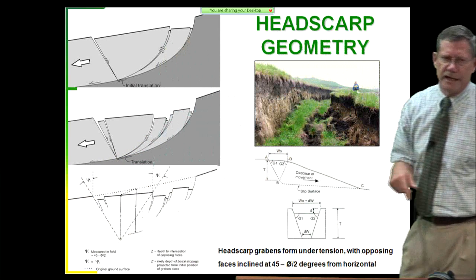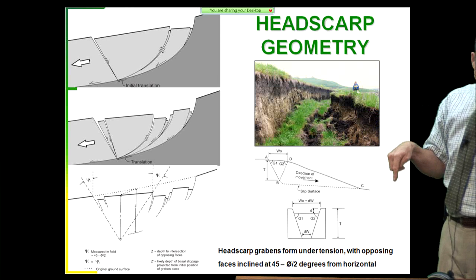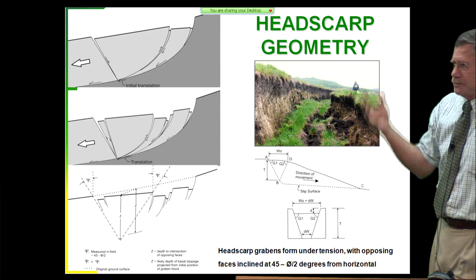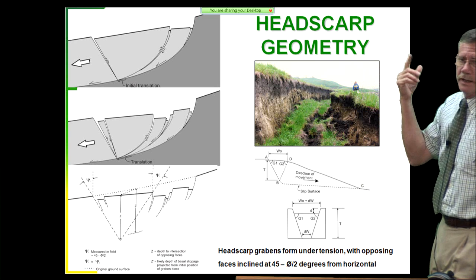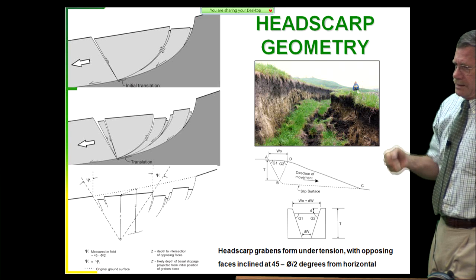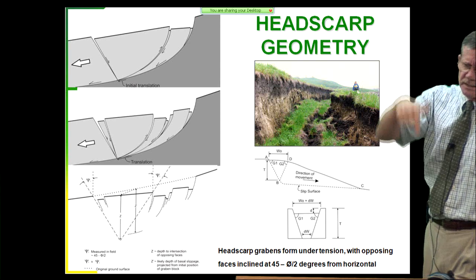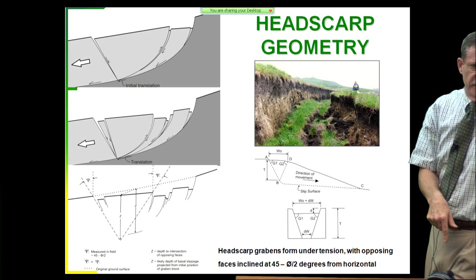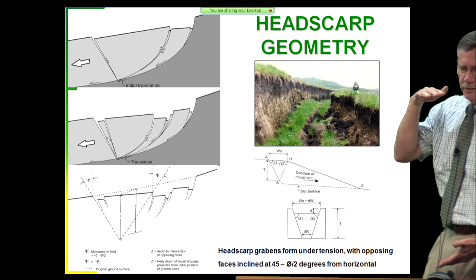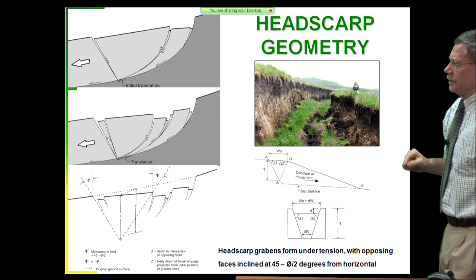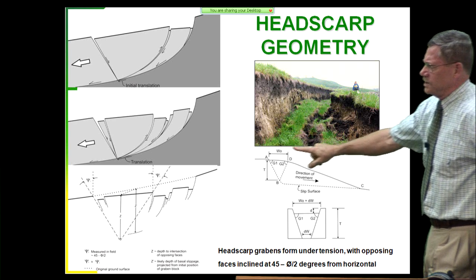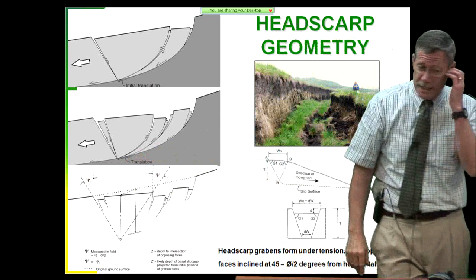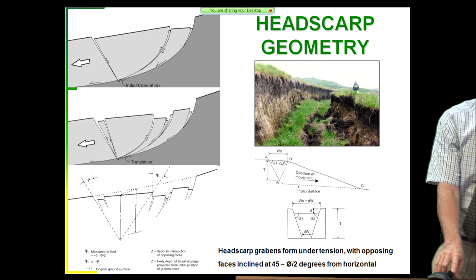Now there's another way of doing that. You would auger first and do what's called a probe. And as you probe down, you probe for the slide plane, you find that, and the driller might say, well, I got a slide plane at 31.5 feet. So they say, okay, pull it all up, move over 2 feet. Let's drill another hole. When we get down to 30 feet, 30.5 feet, we're going to run an 18-inch sampling run, or run a 30-inch sampling run if we're pushing Shelbys, 24-inch, whatever we're going to do. But you always want to probe first, and then you can always do this graphical solution first when you're trying to guess the geometry of the slide for doing a preliminary analysis. These are very useful tools.